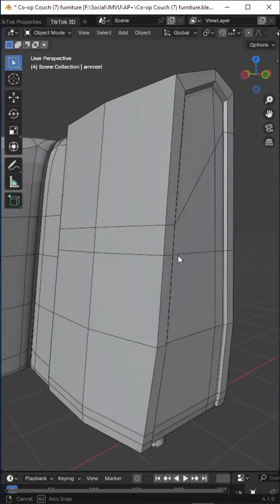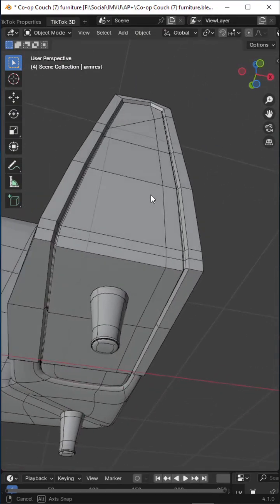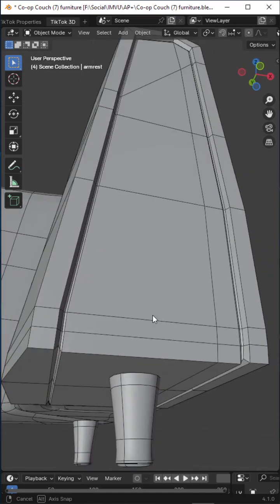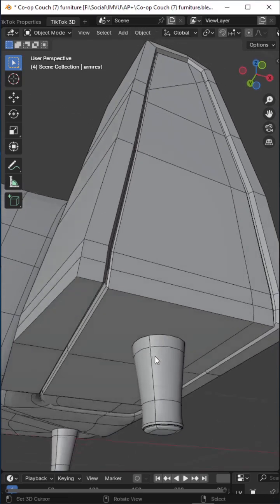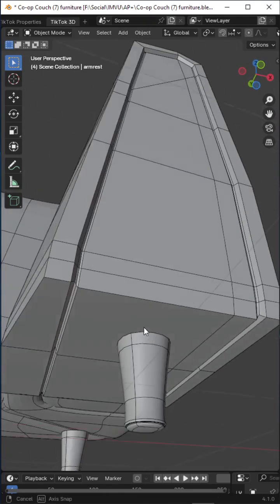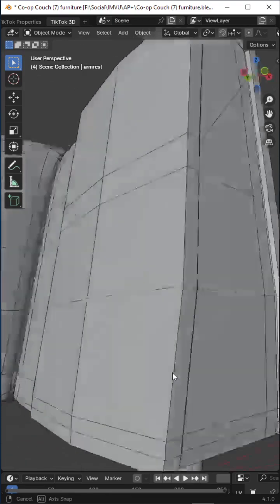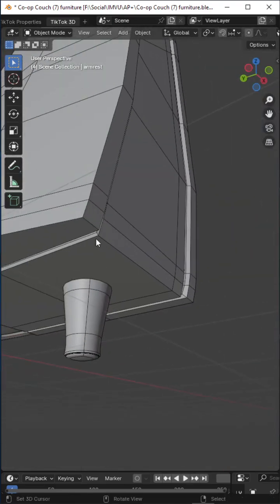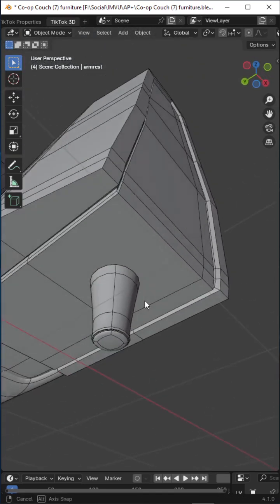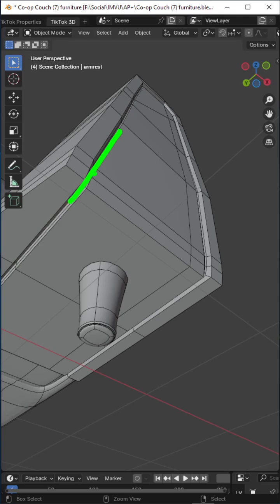That's the underlying cage, the low resolution cage that the subdivision is assigned to. So it is an incredibly simple, very basic mesh, but in order to get this corner at the bottom here to shape itself properly, we have to continue this inset down and around.